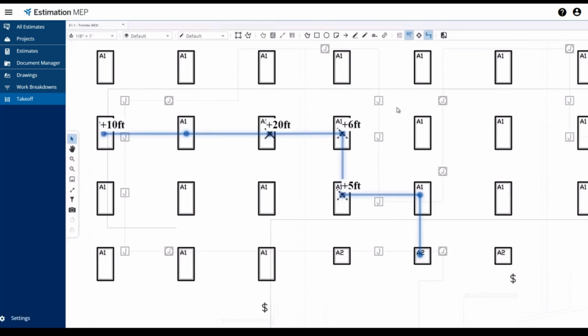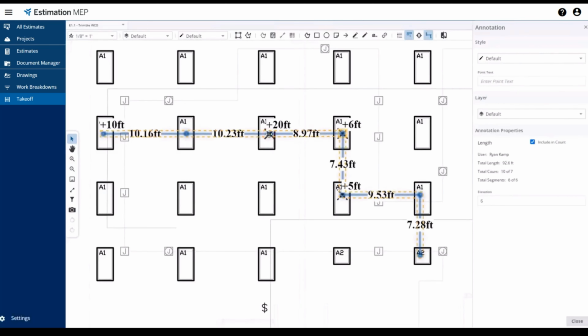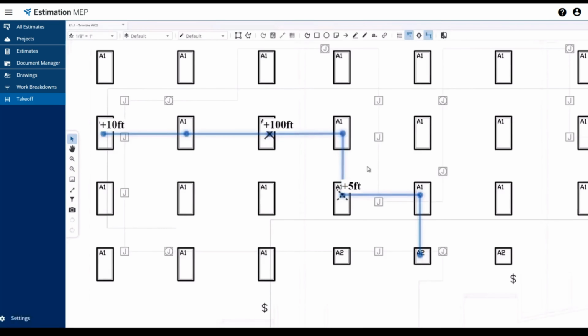If you wish to modify multiple points' elevation, perform a multi-select of the points. So I'll select these 2 points. I will enter in a new elevation value of 100 feet, at which point both points are updated. As you will see, the 2 elevation change indicators were consolidated into one, as both points are now at 100 feet, and the indicator is only displayed at the point in which the first change in elevation occurred.